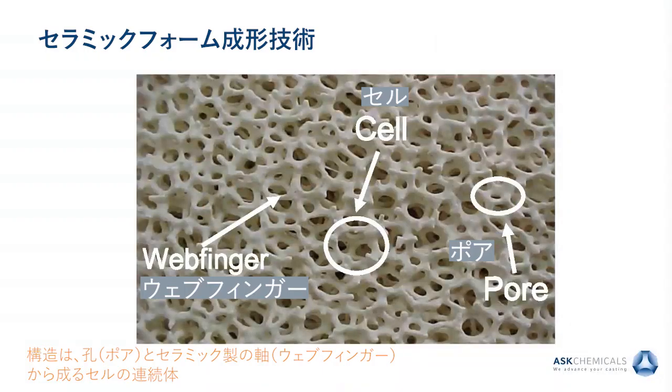Some words about the ceramic foam structure and terminology. By the way, the structure contains a continuous network of voids made up of many pores in typical cells, which you can see here on the picture. The molten metal flows through these tortuous, convoluted pathways, which brings the main advantages of this structure for the foundry guys in pouring: filtration, reducing of speed and pressure, and fulfilling what I mentioned before on the slide, you remember, the requirements by Reynolds number, reducing the V, the speed, and the D, the diameter, which we have seen on the previous slide.